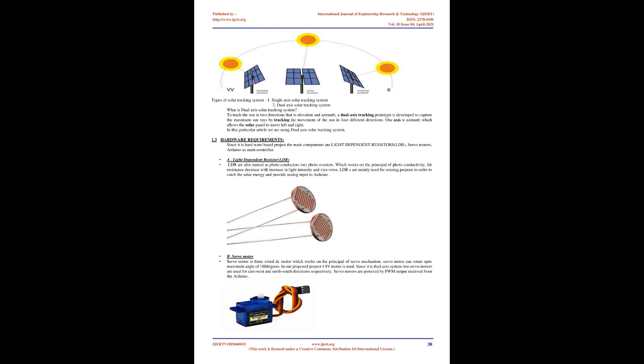The study has also showed the big advantage of the optimized scheme over continuously rotating panel. In fact, it was found that the energy saving on the consumption side is just over 20%. More importantly, during the peak hours where maximum energy is extracted, the panel only rotates for a handful times, in the case in hand only 3 times. On top of that, the beauty of the scheme is that only a single tiny pilot, drawing very small current, could be used to guide thousands of panels.